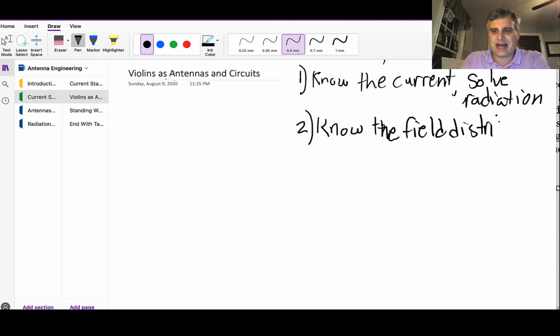And it turns out there's a class of antennas that this works really well for as well. For number one, wire antennas of all sorts of shapes and sizes can be solved this way. For number two, things like horn antennas, parabolic dish reflectors, where if you actually had to solve for the current on these big complicated structures, you would drive yourself crazy. But they're constructed in a way to make the field in front of them relatively predictable.